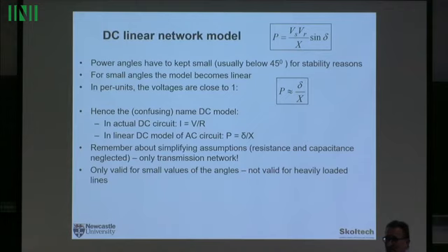So when you talk about per unit, so we have a nominal value, does that somehow get sucked into the X? Yes, but of course, per unit means you have to transform all the variables. So X, you're right, X also would be in so-called per units. It means divided by some nominal value. In power networks, usually we use those per units because it's easier. Because the voltages are equal to 1, and it simplifies the notation. But you don't have to.